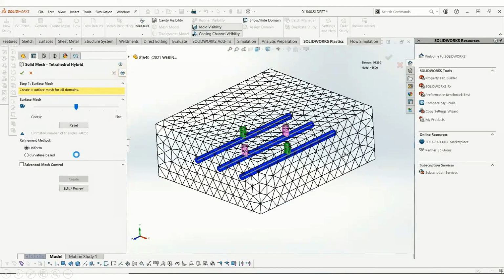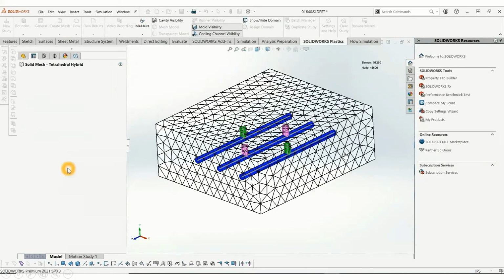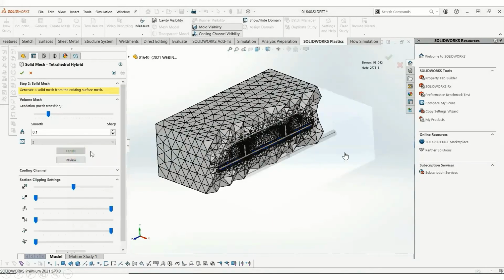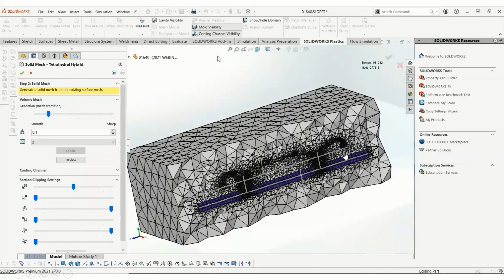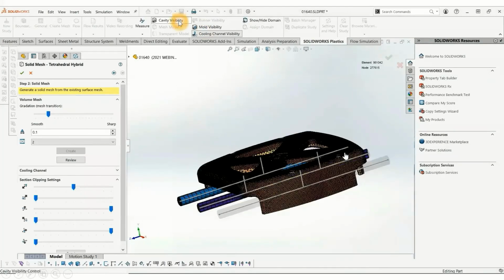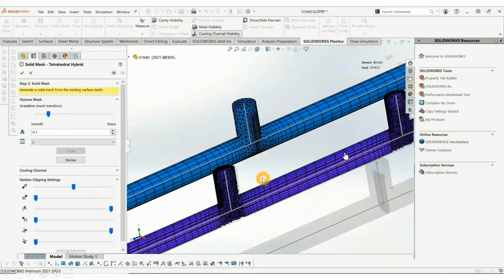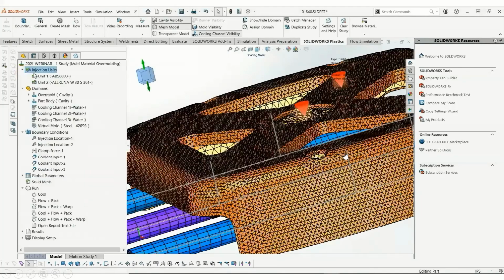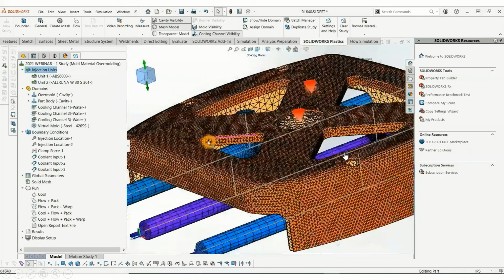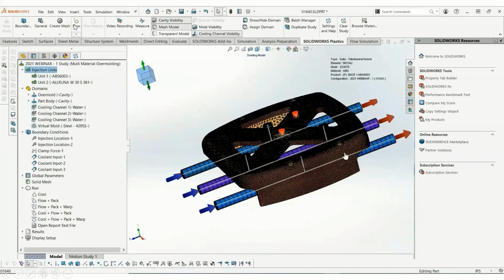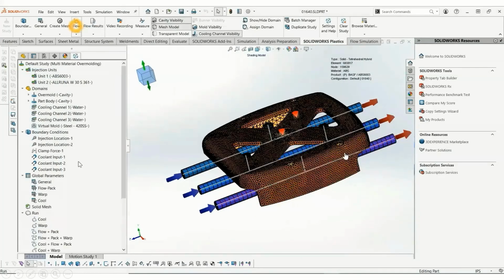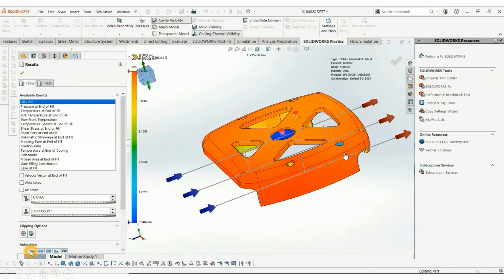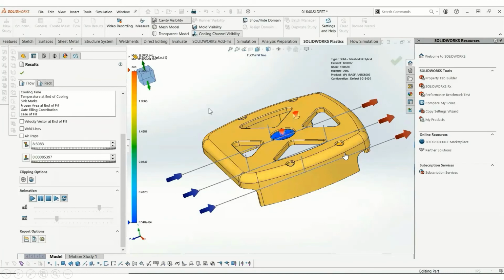Eventually, when you do mesh the model in preparation for the final simulation, you will immediately see the benefit of those improved baffles and bubblers defined earlier. Now, after or during the meshing process, they are fully meshed and modeled appropriately, giving you more accurate simulation cooling results without the need to fully model the cooling channels and the physical components that make up those special inserts.